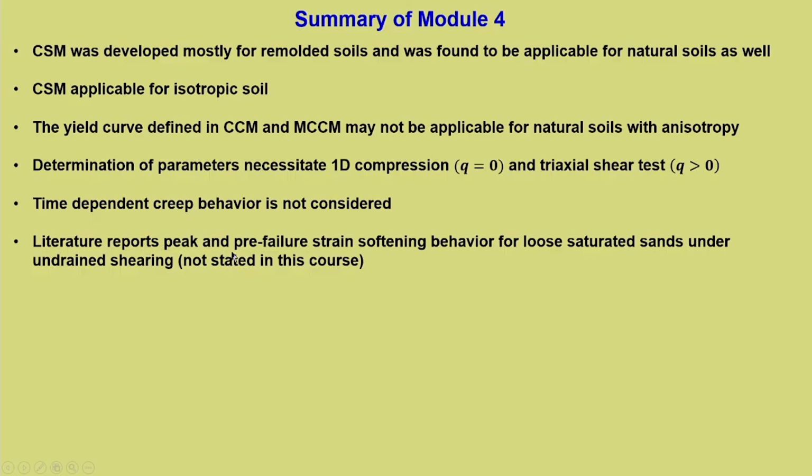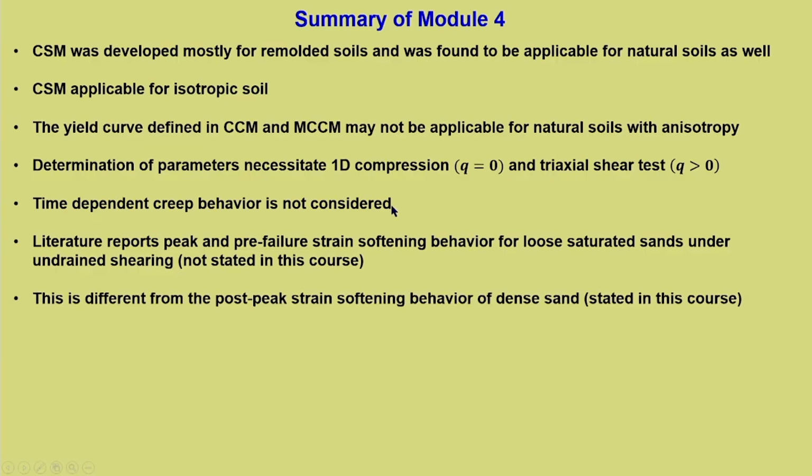So that is why we have not chosen to explain this, and an important difference is that this peak is considered to be due to pre-failure strain softening, whereas the trend which we have discussed is post failure strain softening.